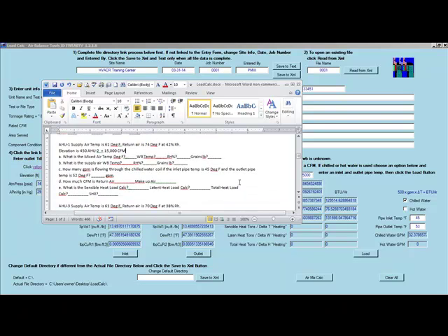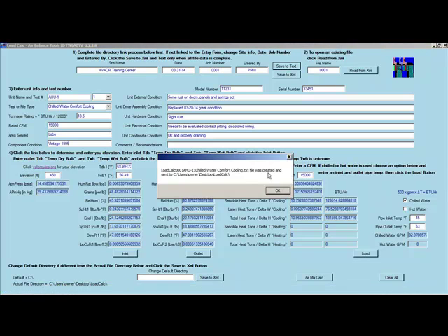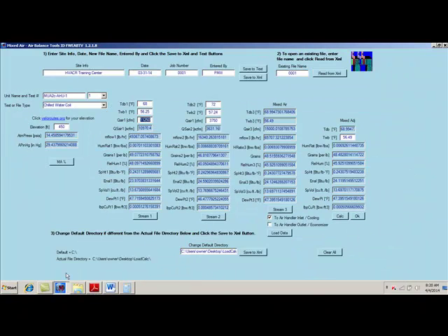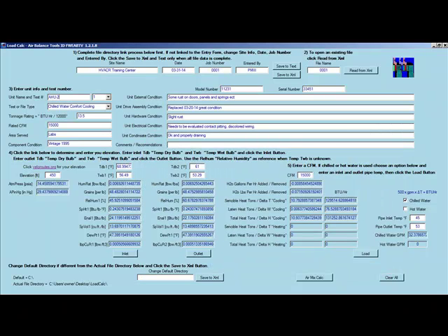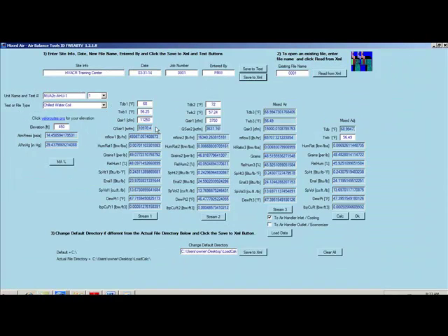Okay, so this one is actually done, so we could save the text, save it to XML, and go back to our mixed air so we can overwrite the existing. In this case, this would be air handler 2. So let's go ahead and go to air handler 2, and let's go to our mixed air for air handler 2. The file names pretty much stayed the same. You want to try to keep the file names the same as you can if you're doing multiple tests.